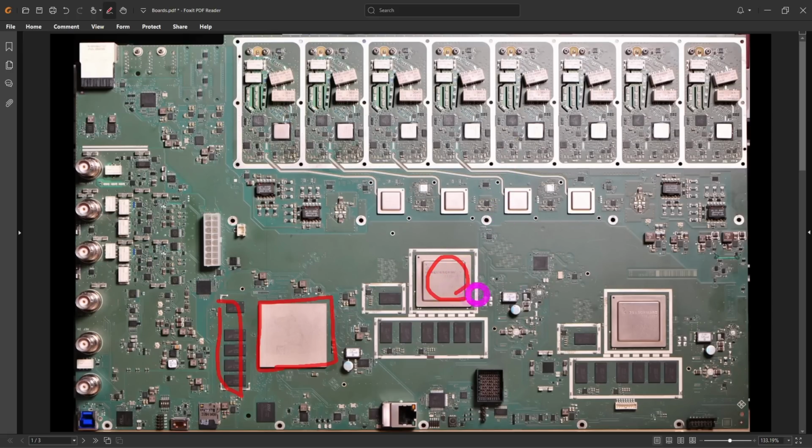So we do have two identical ASICs over here. This is going to be all the memory acquisition, processing, and all the hardware accelerated features we talked about are going to be done in these ICs. And some of that may be offloaded into the FPGA, but given that all the memory is over here, these are the acquisition memories of each 4 channels at a time, it's clear that a lot of processing is done locally over here. Another thing to note is that there are cages around all of these devices, and that's because there's a lot of digital activity, and you're going to radiate out broadband noise from all the interactions of these devices with each other.